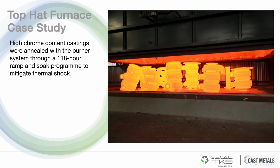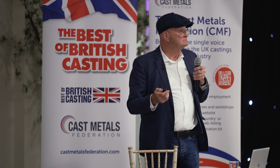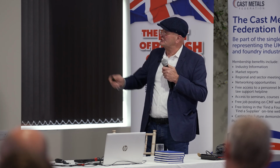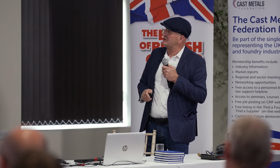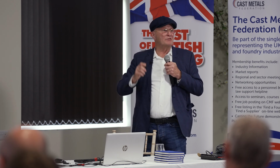This is interesting. High chrome content castings to be annealed from the casting situation to de-stress them. If you heat them too quickly, as you'll be aware in the room, they tend to explode. So they were doing a ramp and soak process of 118 hours, taking it to just below 1,000 degrees.